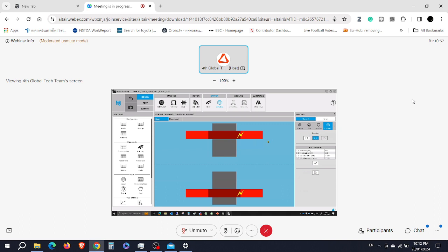As you can see here is the total extension of the end winding. So if you have, for instance, a limit on the length, you have to pay attention to your end winding extension in order to fit the motor in the maximum length you have.